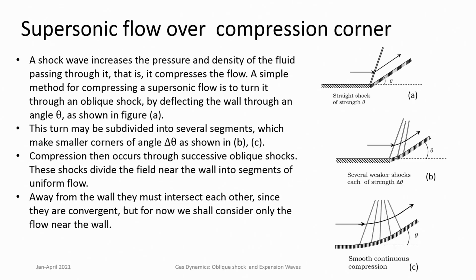The counterpart to that is when the flow turns away from the mainstream. How do we analyze these flow features? Then we saw that you get expansion waves or an expansion fan. So, how do we analyze expansion fans? For this, we begin initially with the flow undergoing a gradual turn towards itself, and understand what happens as the oblique shock becomes weak.